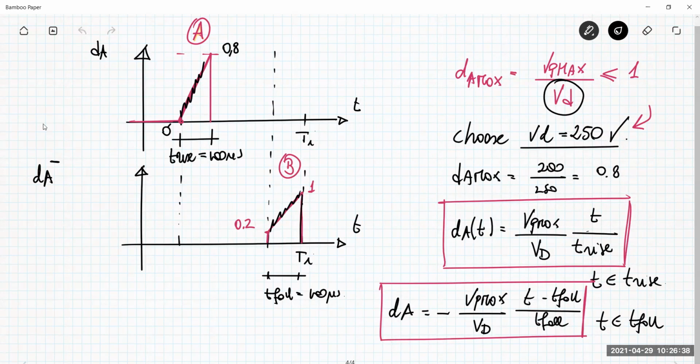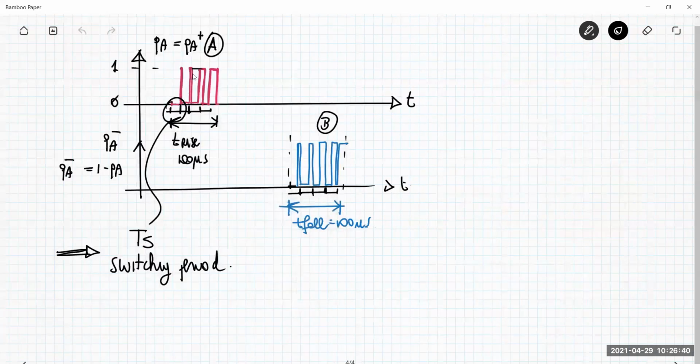If I have just two periods, two pulses in T-rise, can this be done with enough resolution? Is it enough to control, in fine-tuning, the duty cycle? Typically not. I need several periods during this T-rise or T4 interval in order to modify the duty cycle slowly, and to have a variation similar to a linear variation.